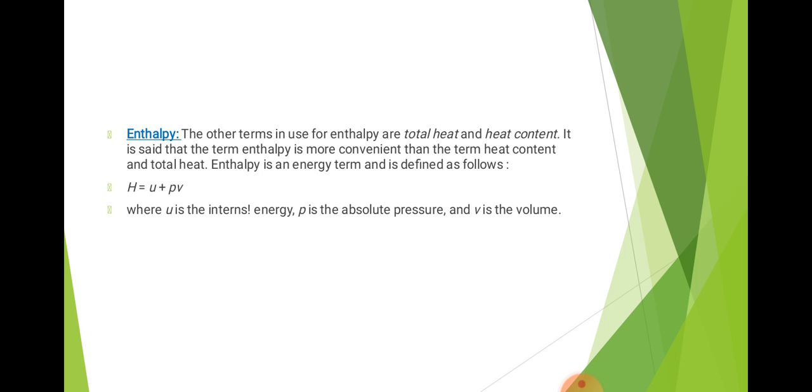Since we cannot measure the absolute quantity of internal energy, it is impossible to measure the absolute enthalpy of a substance. What we wish to know in actual practice is the change in internal energy and change in enthalpy. Wherever the change of internal energy can be calculated and whenever the product PV is known for any two states of any fluid, the change in enthalpy can be calculated.